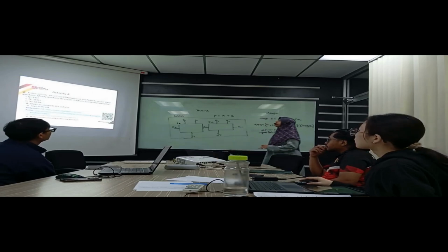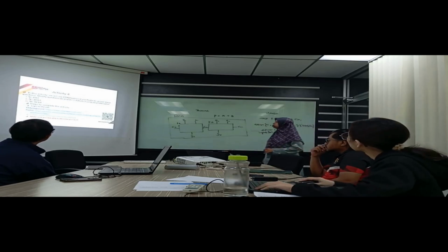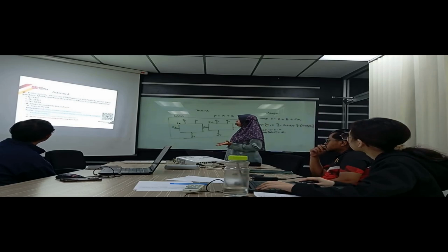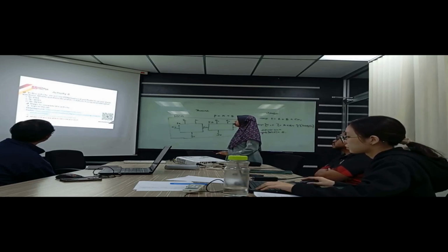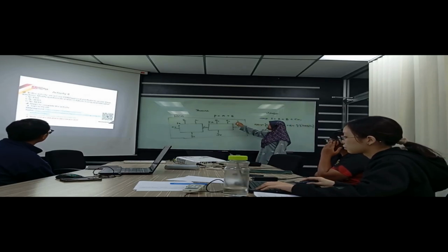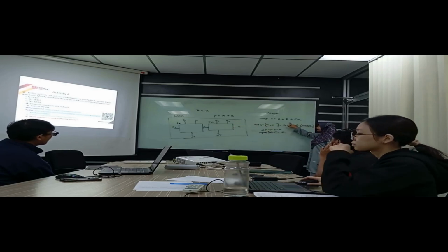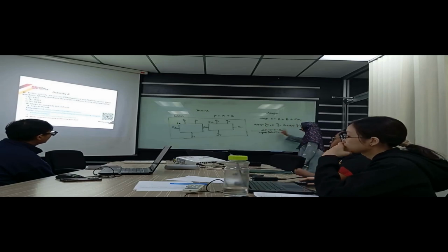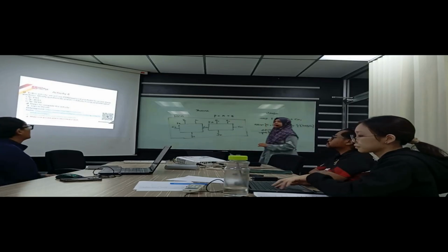Okay, activity 4. In this activity, modify the question previously in activity 3, B and C, using parameterization: N equal to 8-bit, N equal to 16-bit, N equal to 32-bit. Previously you used structural modeling and you also used data flow modeling. Then here you just call this module back and change to the new bit only.